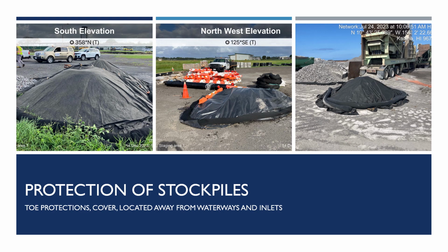Contaminated soils must be disposed of at a DOH-approved facility by a DOH-approved transporter. If contaminated soil is encountered, refer to the Contaminated Soil Management section of the Construction Activities BMP Manual for required actions by the project team.